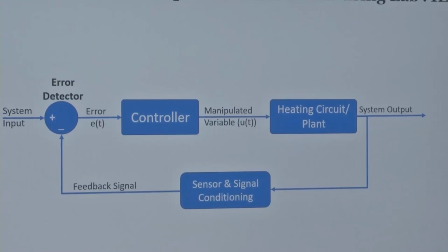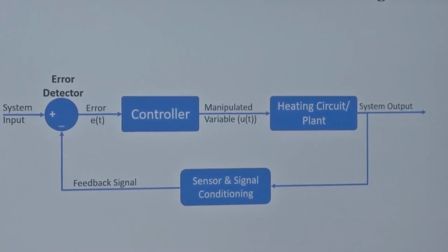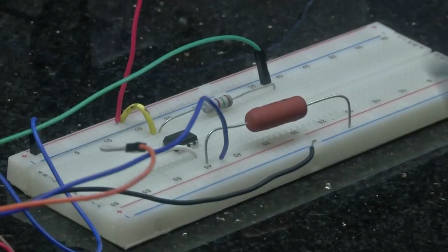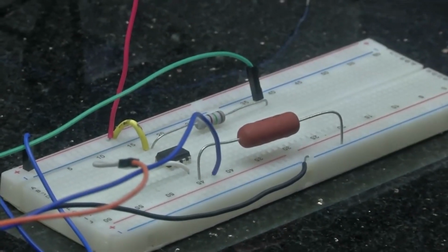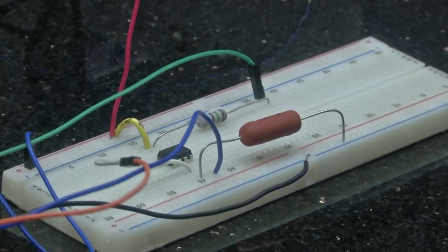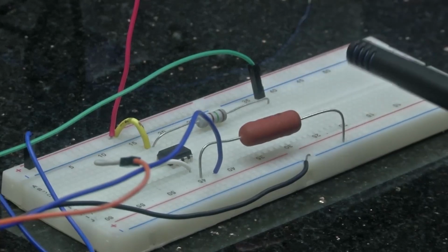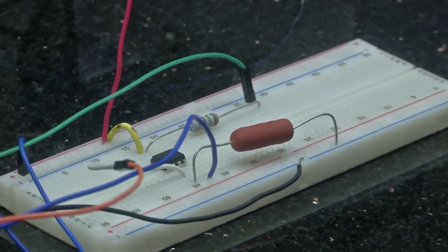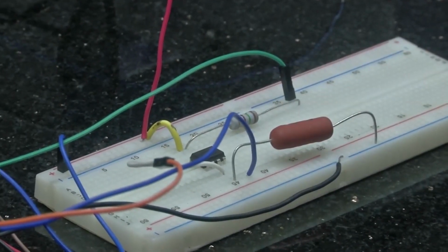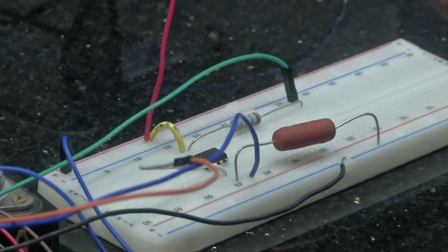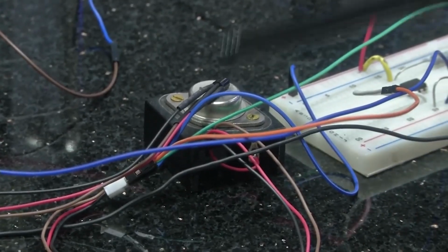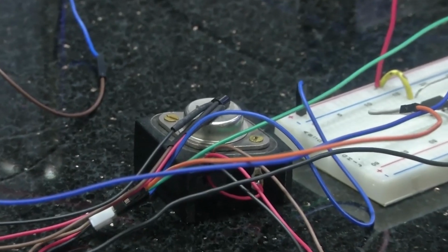First, in order to make you understand, I would like to show the circuit that we are going to use. If you look at the breadboard, that is the circuit we are using. This is a 741 op-amp, and this is a 180 ohm resistor which we have seen in the circuit, and this is a 5 watt 0.1 ohm resistor. It is connected as shown in the previous figure, whereas this is our 2N3055 transistor, and on top of it I have attached an LM35, which is a temperature sensor.